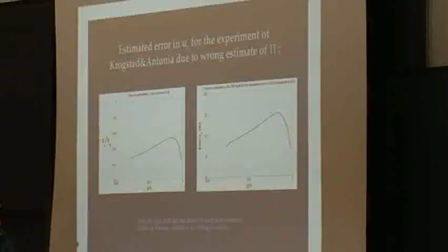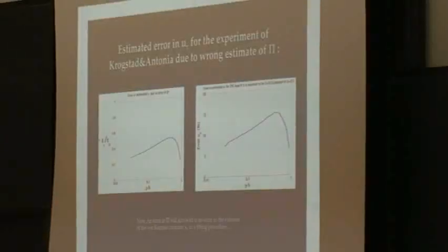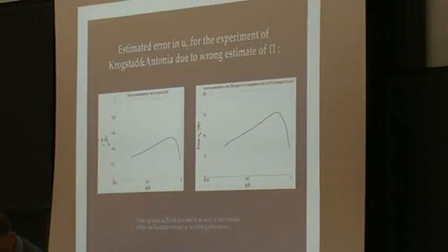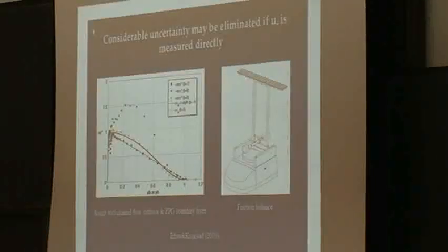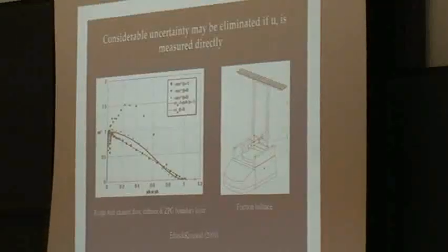And that's a very large uncertainty, and it's worrying, especially because u tau is our main scaling quantity. So if you have an error in u tau, you will have different shear stress profiles, and you will get a different shift in the log law. So I would have liked to measure the wall shear from first principles. And as I said, I can't use the oil technique because my surface is irregular. And so we designed this very, very simple surface balance.